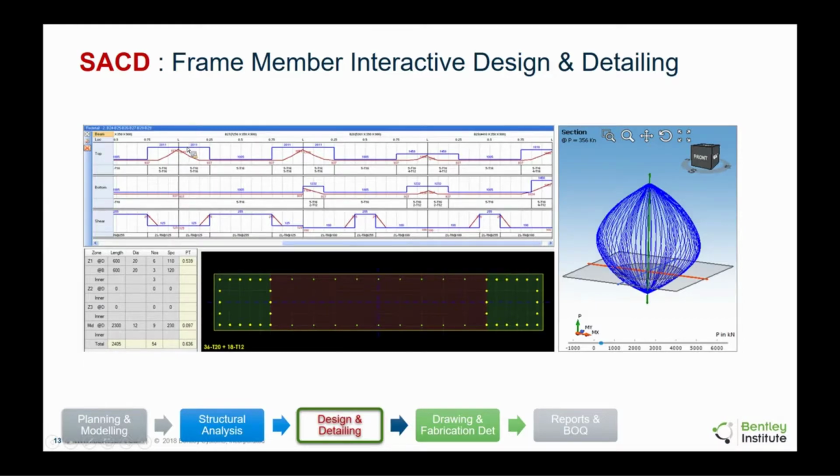So they're superimposed. Consequently, as an engineer, you can visualize what's happening, and then you can also make changes here. And as you keep making changes, the graphs will keep updating to reflect your current change. So for example, if I don't want to curtail rebars here, I want to continue, I can just say continue this rebar here. This line will become straight, indicating to you that you're providing this reinforcement here. It might be more than required, but that's your decision, right? As long as it doesn't violate safety and code provisions, the software will not object.